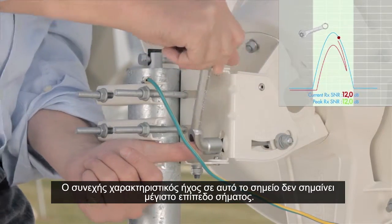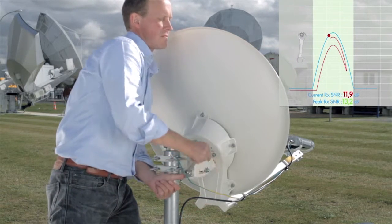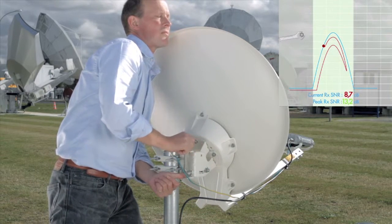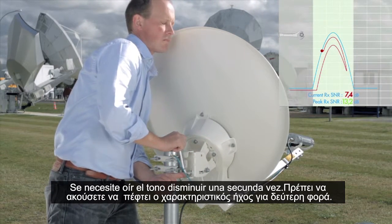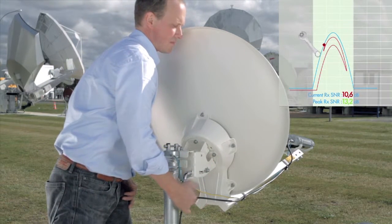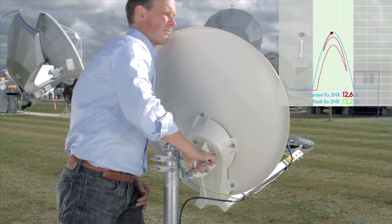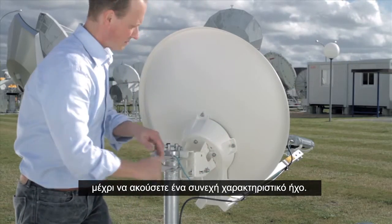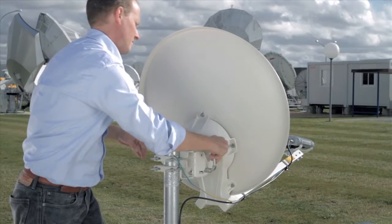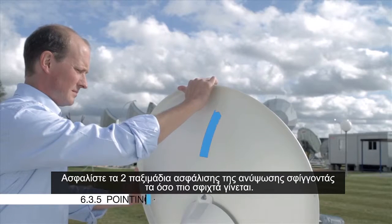The continuous tone here does not indicate maximum signal level. You must hear the tone drop a second time, and then change direction. Now you make very small movements, slowly, very slowly, until you hear the continuous tone. Lock off the two elevation locking nuts as tight as possible.